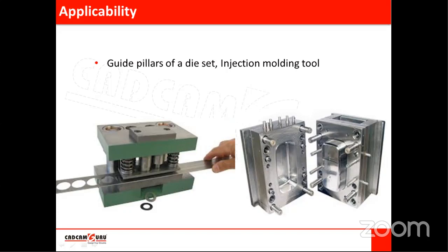After ejecting, these two parts are assembled again and molten plastic is injected inside the cavity. If alignment is not proper, we can get different thicknesses on different sides. If this gets shifted to the left-hand side, then here the thickness of the component will be small, and here we will get large extra material.